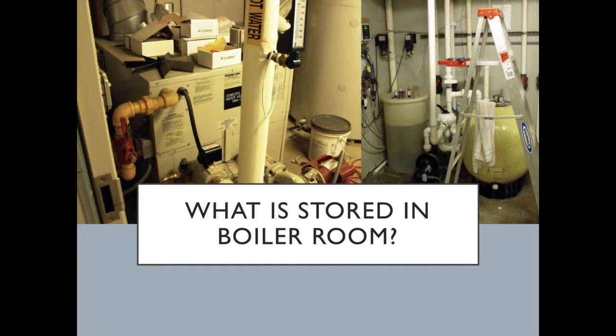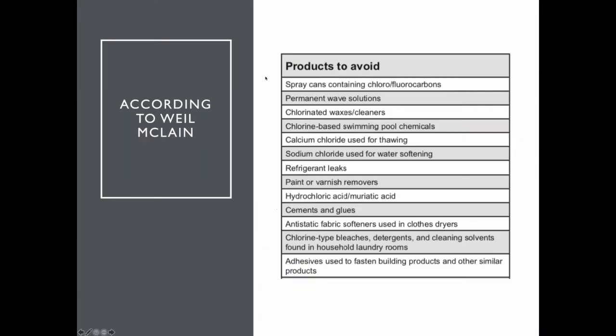Like what's stored in a boiler room? This was a healthcare facility, and it had all kinds of chemicals in there, and it was off-gassing, and you could see they were going through all kinds of igniters on the lock bar because they didn't react well with the stuff in the tanks. So make sure your boiler room's able to breathe, and make sure that it's safe inside there and there's not chemicals that are going to react.